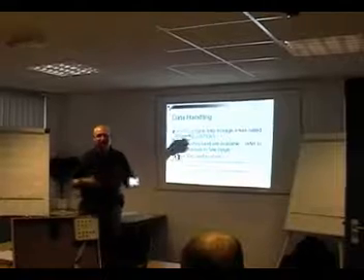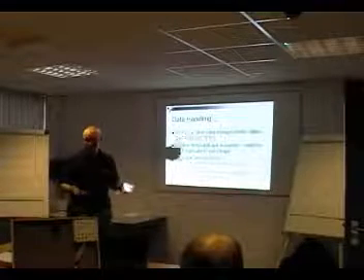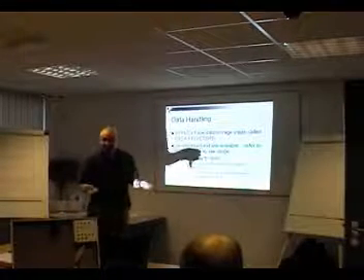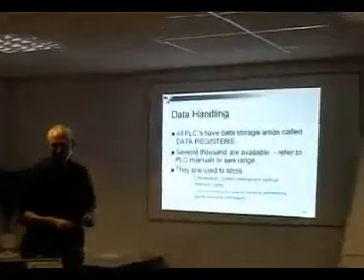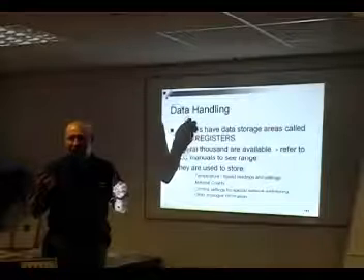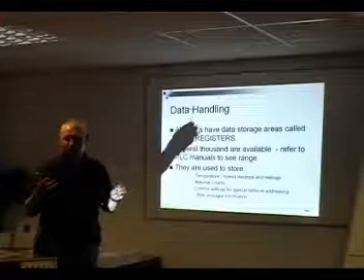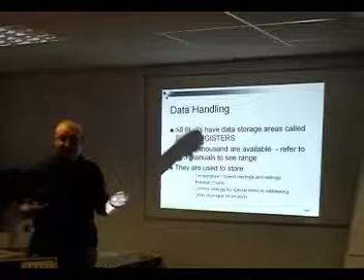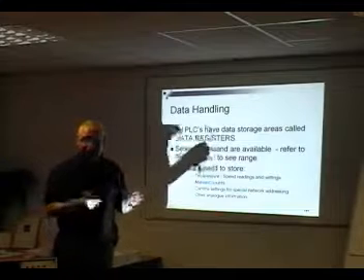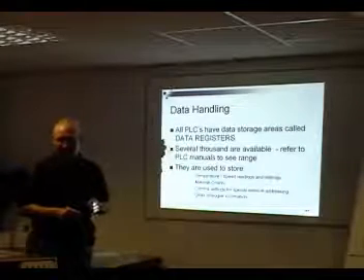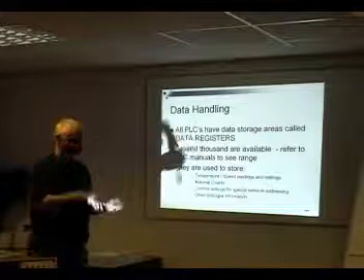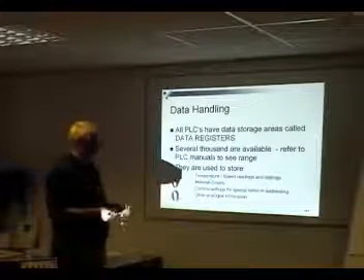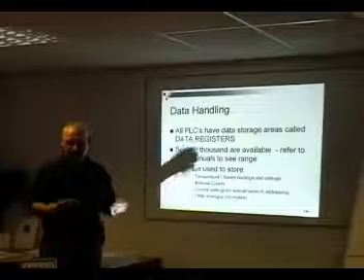But if you're counting materials in production output, then you don't normally use a counter. In fact, you would use a data register, and you would use what we call an increment function, which will increment the value inside of the data register. We'll look at that later on. Yeah, so at the end of the day, they can say, okay, we've done 30,000. 30,000, that's right.